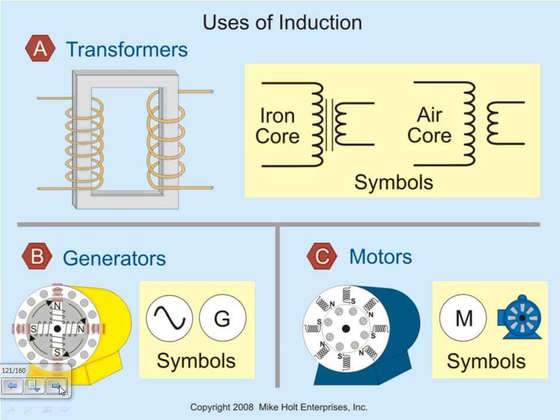You bring a current to the transformer right in here, and a voltage. This voltage, by moving through this coil, will create a magnetic field. This magnetic field induces a voltage into the second coil. This is where the mutual induction happens. And I got myself a voltage on the secondary that's completely different than the voltage in the primary. Here's your transformer.